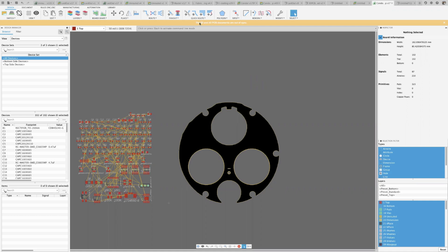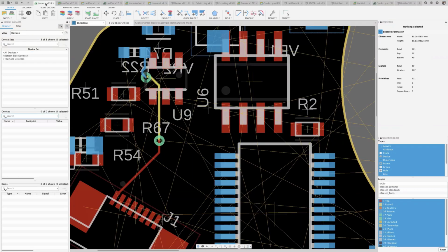You're going to get this message here that it needs synchronization, but I wouldn't be synchronizing as of yet, because I've got to start moving the parts into the board. So I wouldn't push it to the 3D PCB as of yet. Now, I've done some work already on this circuit board. So I already have it laid out, but it's fully unrouted. So let me show you what it looks like right now.